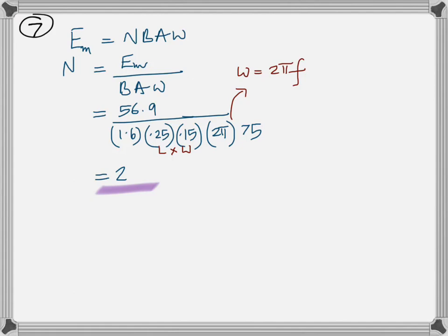Two pi times f. What is the applied EMF? 120 volt. And so when it picks up, you know that the greater the speed, the bigger the back EMF. So when it is operating at maximum speed, the back EMF is 105 volt.